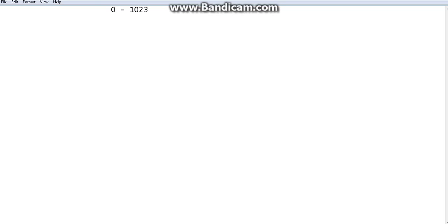So what I am going to do is say, okay, we are going to read the analog input value from the variable resistor. It is obvious, right? If the analog value is less than 511, that means the half value, then we will go for a 500 millisecond delay blink of that same LED scenario. Otherwise, that means else, or in other words greater than 511, yes or no? Yes. We will go for 1000 milliseconds.